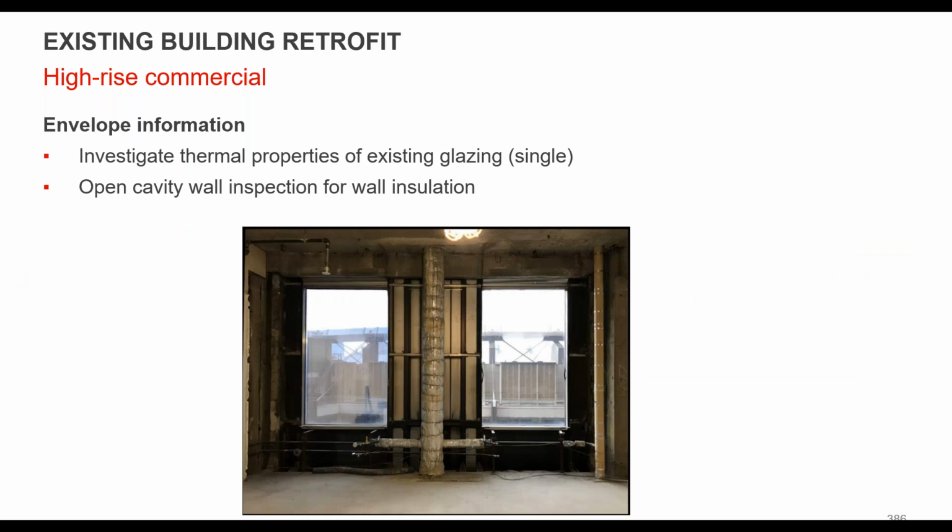There's three big ones. One was the plug load nighttime stuff. The second big thing that was changed as part of this was the facade. So this is from the inside, once we've stripped out all of the chipboard and looked at what was behind the wall, basically. There was very little insulation. It kind of compacted down to the bottom below the window.